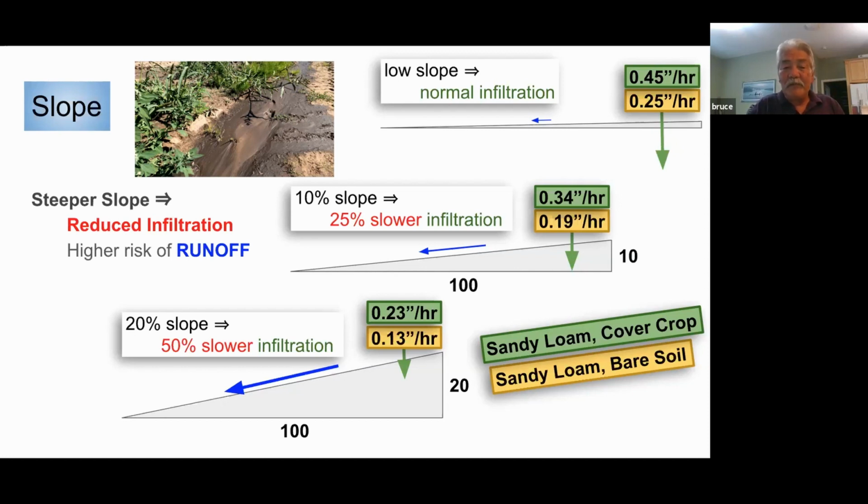You want to possibly look at the direction you're running your lateral in. If it's a new piece of land, is that the right direction, or how could you minimize it? Could you have a header line in the middle so that all of the slope wouldn't be in one section? You'd have to really evaluate the best way to do that. Next.